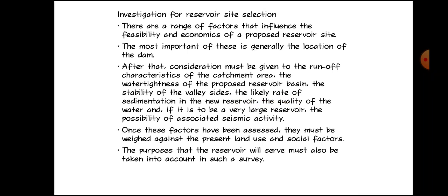After that, consideration must be given to the runoff characteristics of the catchment area, the water tightness of a proposed reservoir basin, the stability of the valley site, the likely rate of sedimentation in a new reservoir, the quality of the water, and, if it is to be a very large reservoir, the possibility of associated seismic activity.